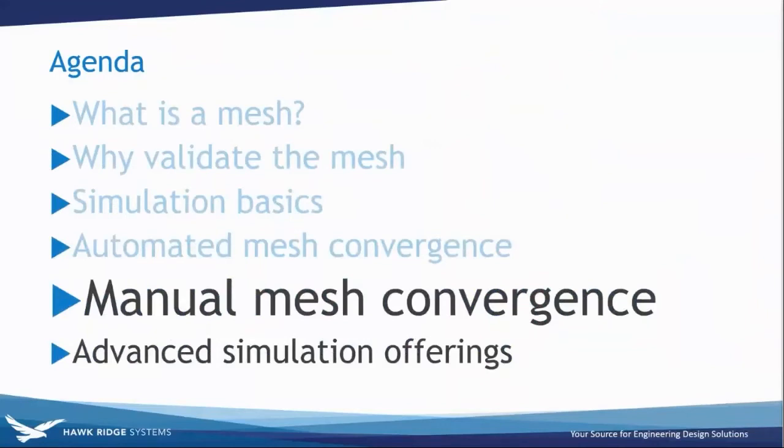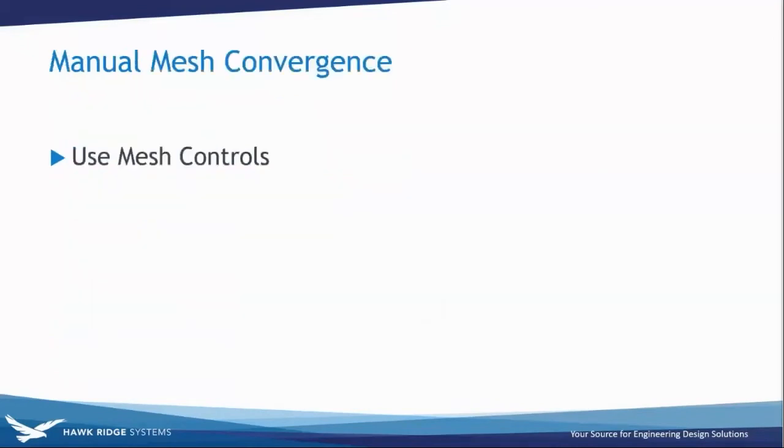So the automatic mesh convergent tools were great at finding singularities and proving convergence in our area of maximum stress, but we still have not proved our solution in that cylindrical connection. So now we're going to look at some manual mesh refinement techniques for that.